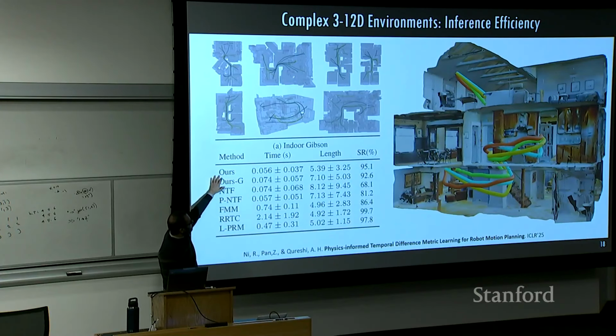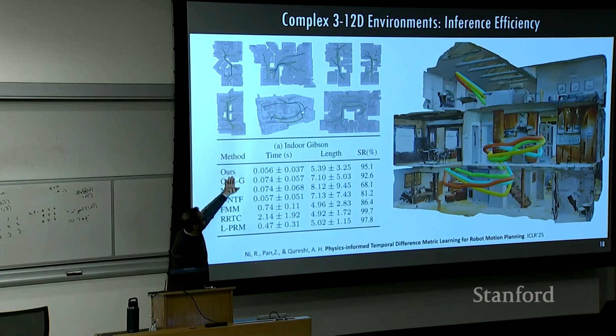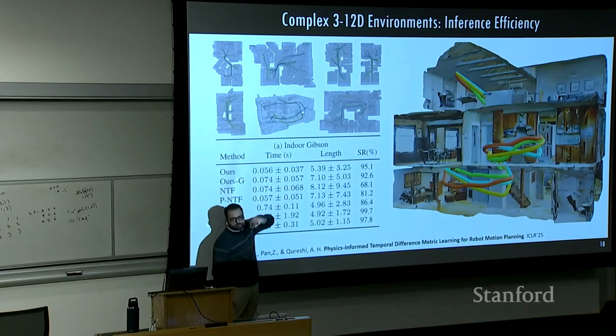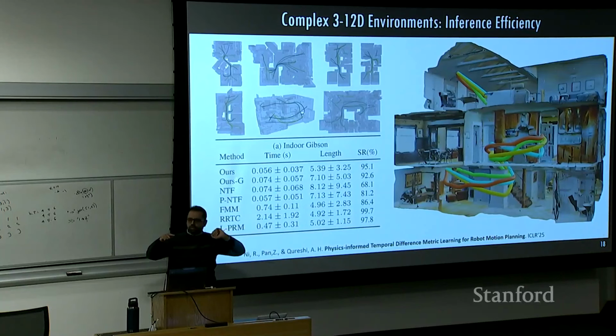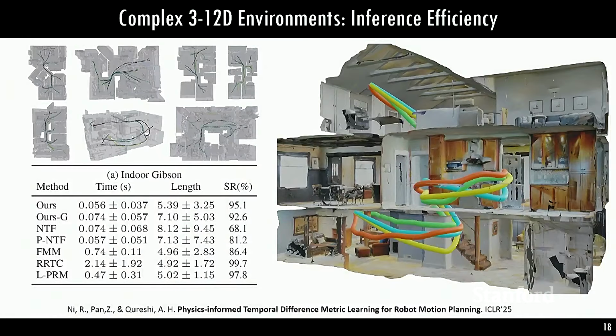There is a difference: because it's a value function, you can incorporate this value function into MPC or MPPI. Any available tool that can use your value function, you can even incorporate it into trajectory optimization. We show that if you combine it with MPPI, it is much faster, because then you don't need to compute the gradient. You just use the prediction directly, the cost-to-go or the value function output. But you can also use the gradient of this travel time to find the trajectory. The computation time does not increase significantly and the success rate is high.